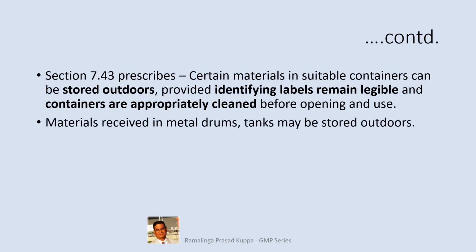Materials received in drums, tanks may be stored outdoors. Generally, high boiling solvents or highly stable materials are received in 200-liter strong mild steel drums or tanks in huge quantities. They can be stored outdoors provided that the material inside is protected from any degradation.